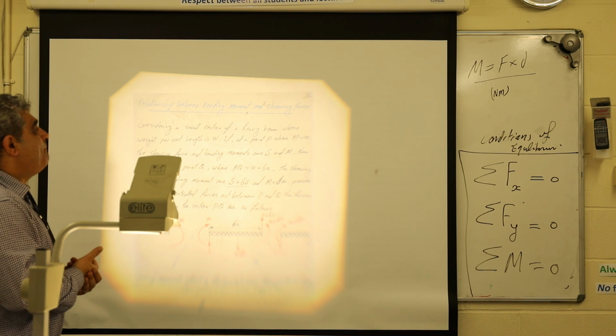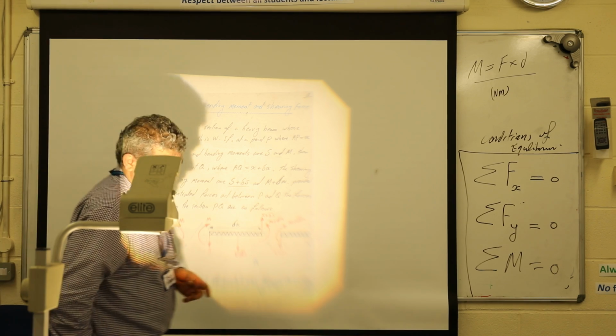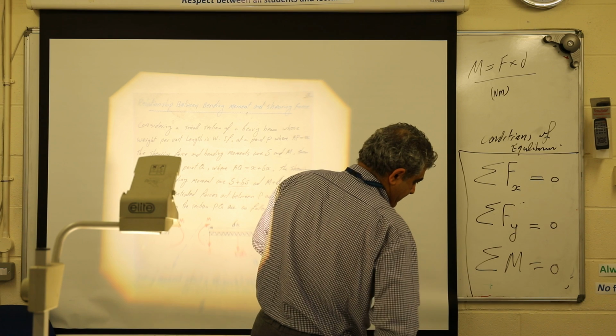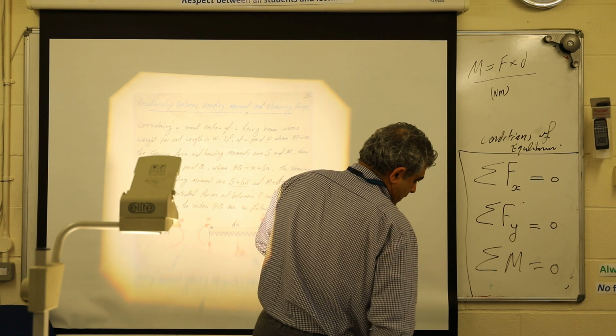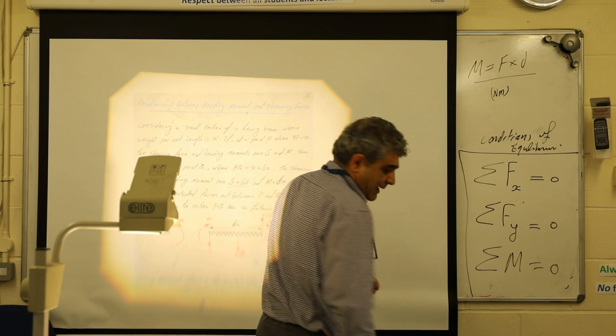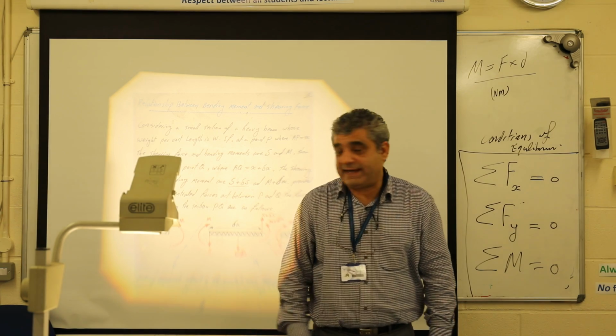The shearing force and bending moment are S and M. As I told you, it's a point A here. I'm going to cut it at this point. Yes? There would be a shear force here, and there would be a moment at this point as well. And the distance from the point to the cut, I call it X.